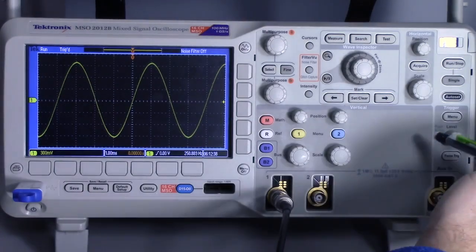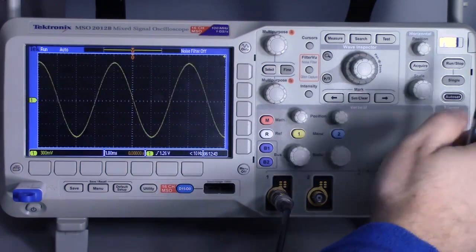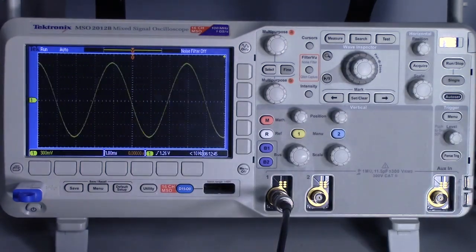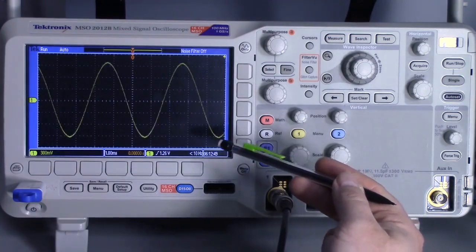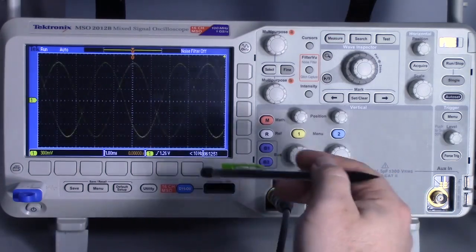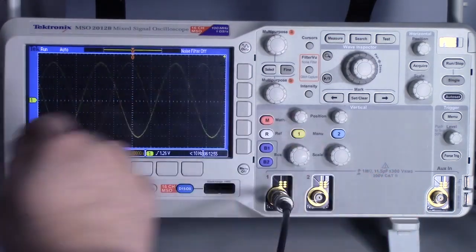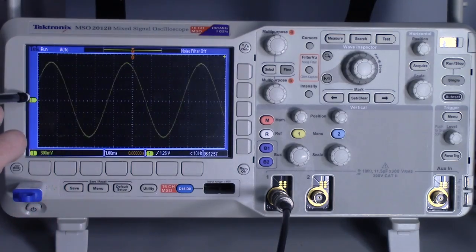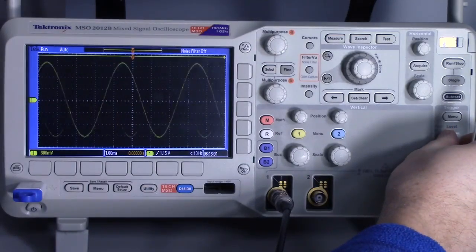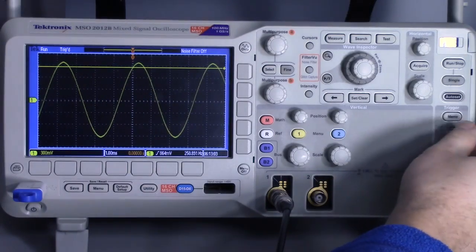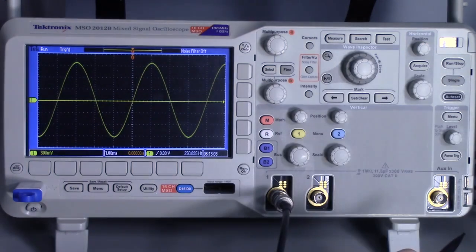Now, one of the things about the trigger is that you might turn it on, and it's doing all kinds of fun things like that. The reason this is doing that is because you don't have the trigger set. So you can look down here and be like, oh, it's 1.26 volts is my trigger level, and I've got 300 millivolts per division, and it's like, oh, I'm above this, so I'm off the screen. And when that happens, just move your trigger level, bring it down, and we'll keep it at 0.